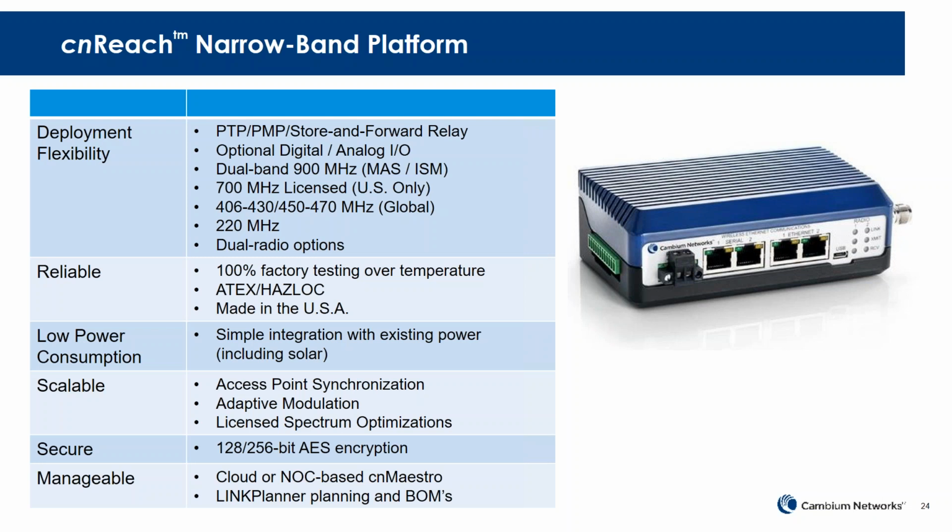The 400 megahertz bands around the world, and then we're just now launching, and this is actually available today, our 220 megahertz solution, which I'll talk about in a little bit more detail. Reliability is important. We test every one of these radios from negative 40C up to plus 85C in the factory. That's both a functional test and a burn-in test. So we make sure that these are operating and communicating at the widest temperature range.